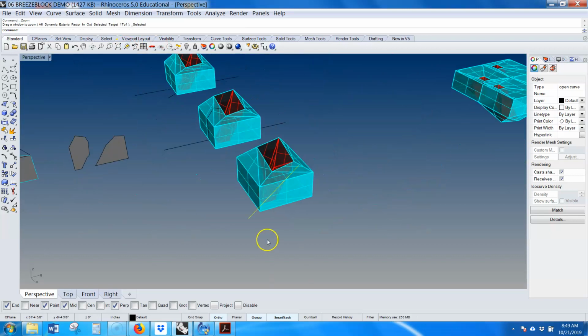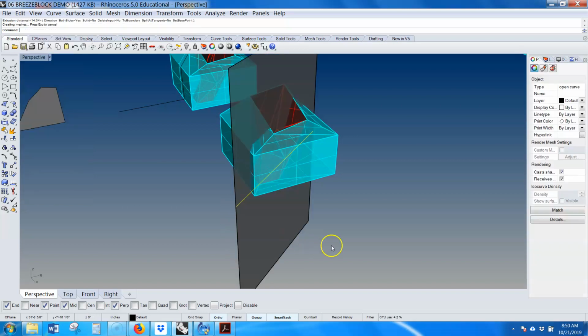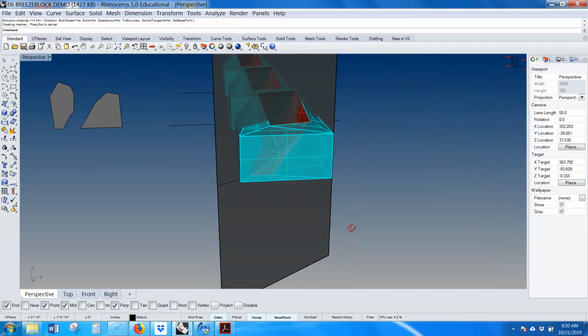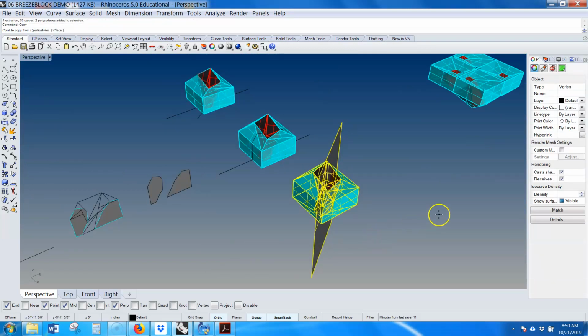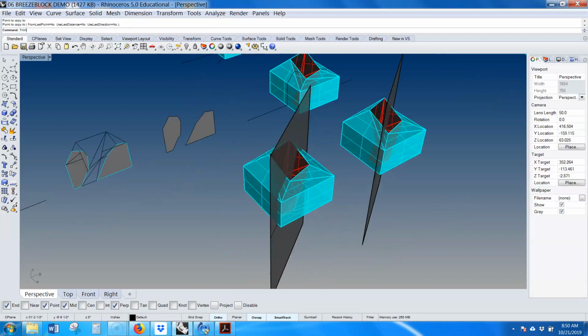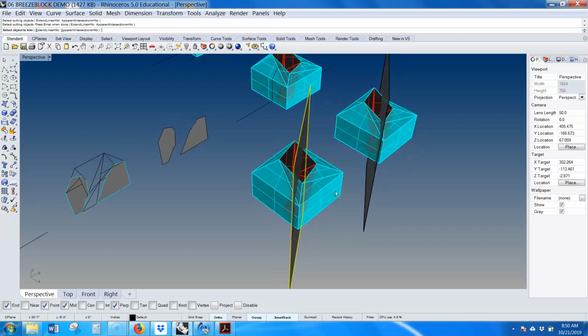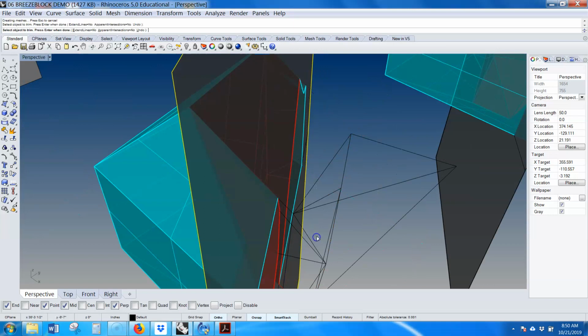Sorry, let's extrude this curve. Again, make sure you're cutting all the way through it, which we are here. All right. Let's trim it off. I'm going to type trim, select cutting objects. I select the plane, click enter, and now select objects to trim.